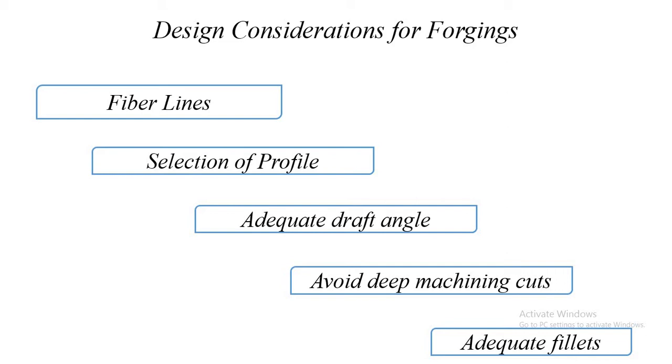Second, selection of profile. The profile selection is important in forged component design. The design should be made in such a way that the fiber lines are parallel if the forged component is subjected to tensile force and perpendicular if the forged component is subjected to shear force.